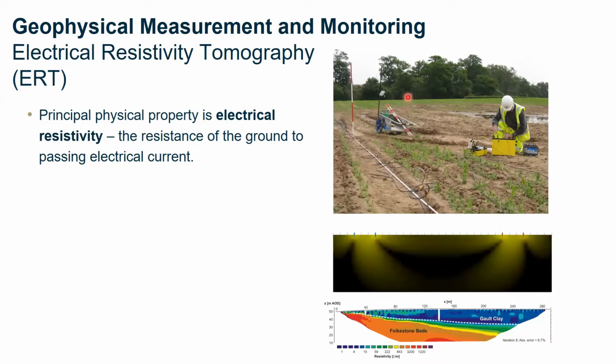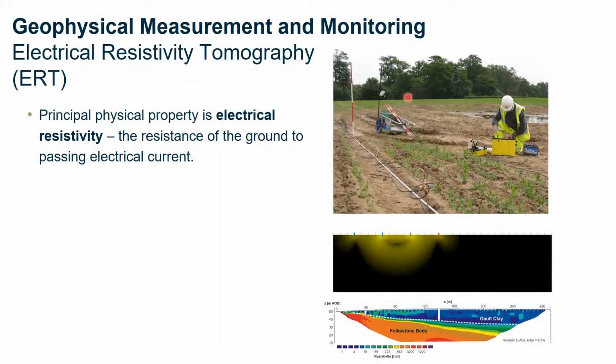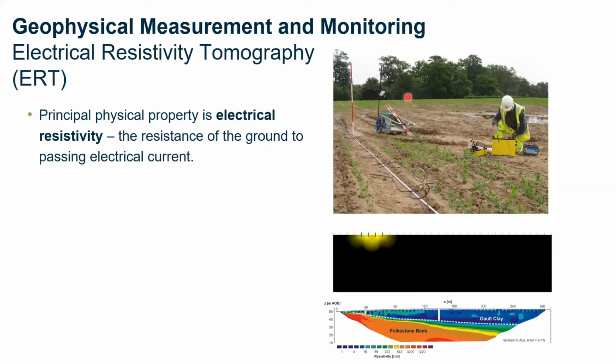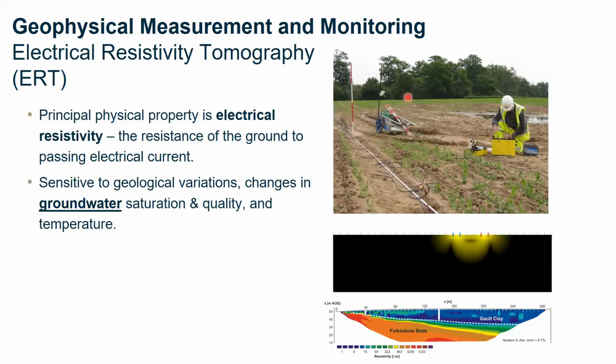So usually, to be able to build up models of the resistivity, we measure along a set of electrodes. So we repeat these measurements either along a line of electrodes or a grid of electrodes if we want 2D or 3D imaging capabilities.